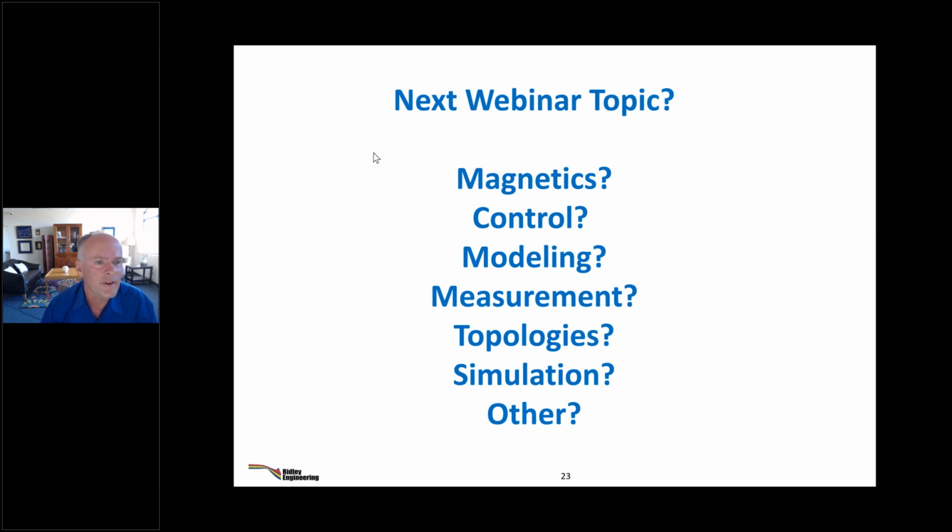How about gap field loss when using foil? Don't put the foil near the gap, and then you don't have a gap field loss. And we can cover that in a future magnetics seminar. But yeah, don't get your gap near the foil. It's always that answer.